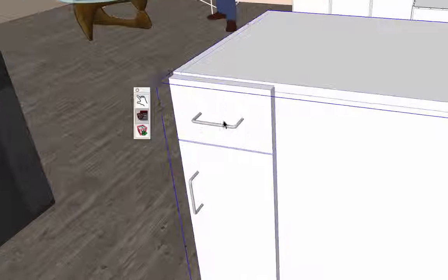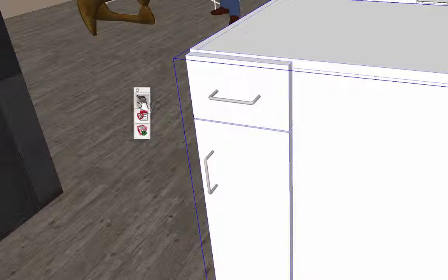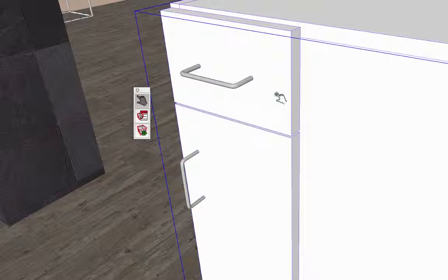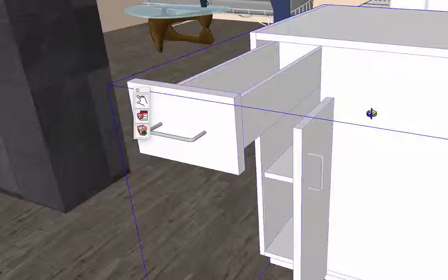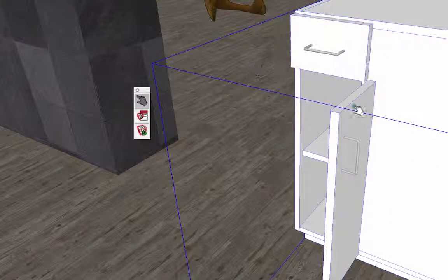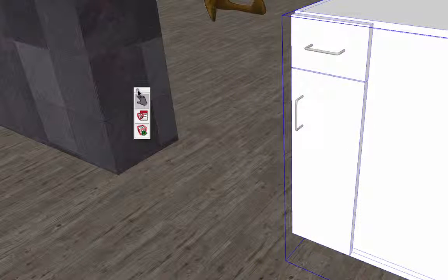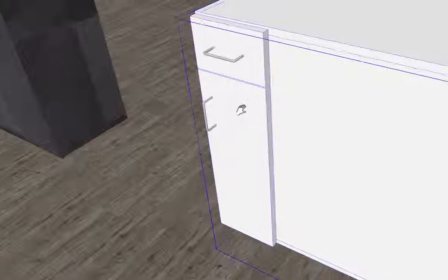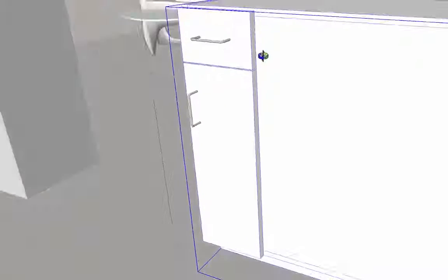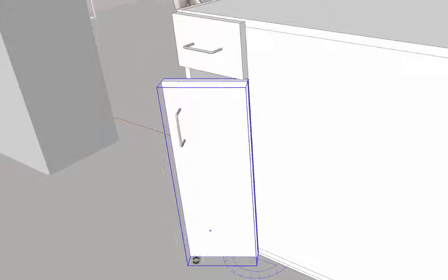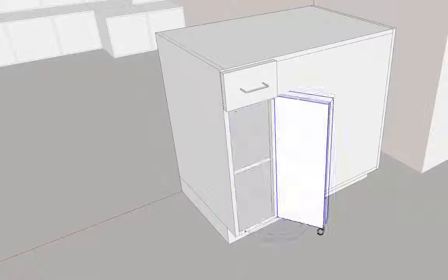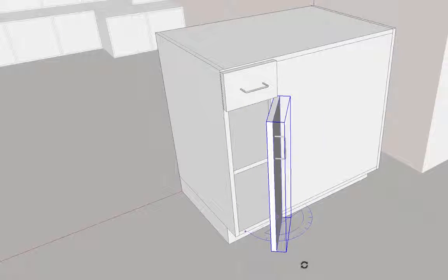Another cool thing is I can use this little magic finger. If you hover over different objects, you'll see that that little icon indicates that something can be animated. So this is nice for space planning. You can click and do a quick animation for certain objects. Of course, not every component's going to have that ability, so you can certainly do the same type of action with perhaps the rotate tool here. So I can rotate this drawer or this door out and see, maybe it helps me for space planning and understand how that affects the space that it opens up into.